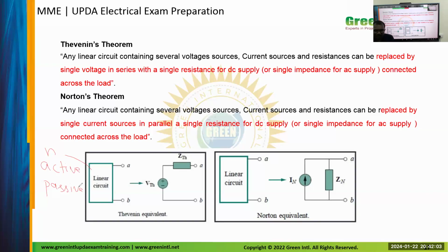So many components are there. And finally, we take the two wires connected to the loudspeaker. The loudspeaker we call the load resistance. So that is here. The complex circuit has n number of resistors, all the things, and the external part is the load, only a loudspeaker. Okay. So by using this theorem, the complex circuit is converted to a simple circuit.